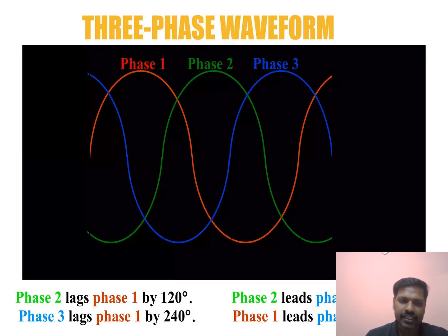To summarize, the three-phase system consists of three AC voltages of equal magnitude separated by 120 degrees in phase. Compared to a single-phase system, three-phase systems are more efficient, use less conductor material, produce uniform torque in motors, and are the backbone of modern power generation, transmission, and distribution.